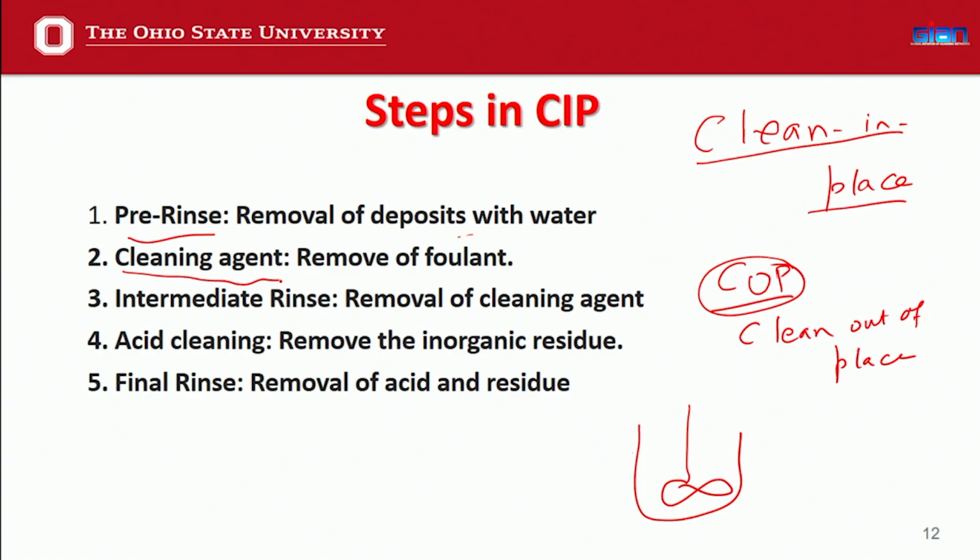The second step is your cleaning agent. You may be removing the foulant by adding some type of cleaning agent, like a detergent. So, you add some detergent to your water, and then you pass it through this whole entire area again. You do this at a certain concentration of your detergent, at a certain temperature, and for a certain time.